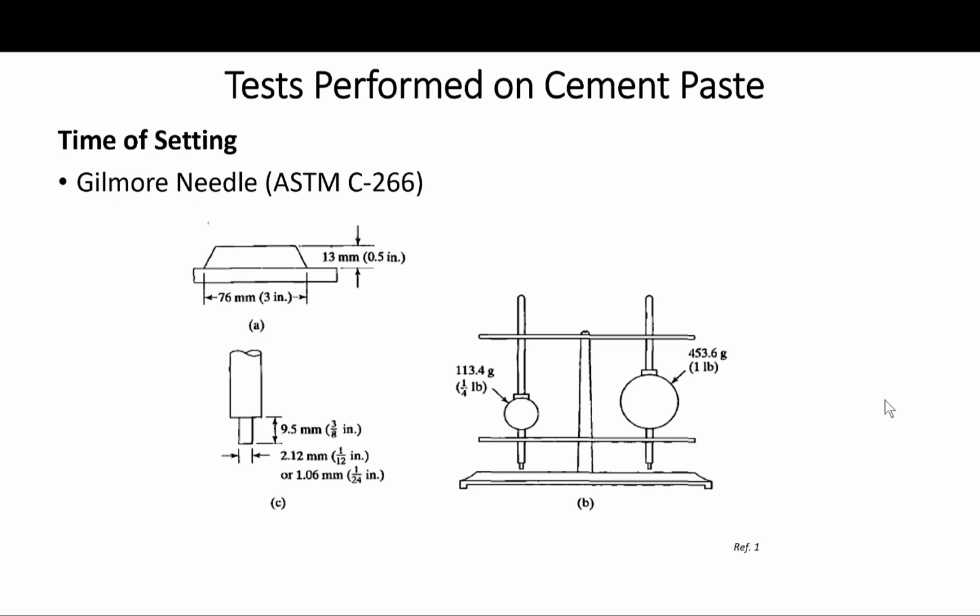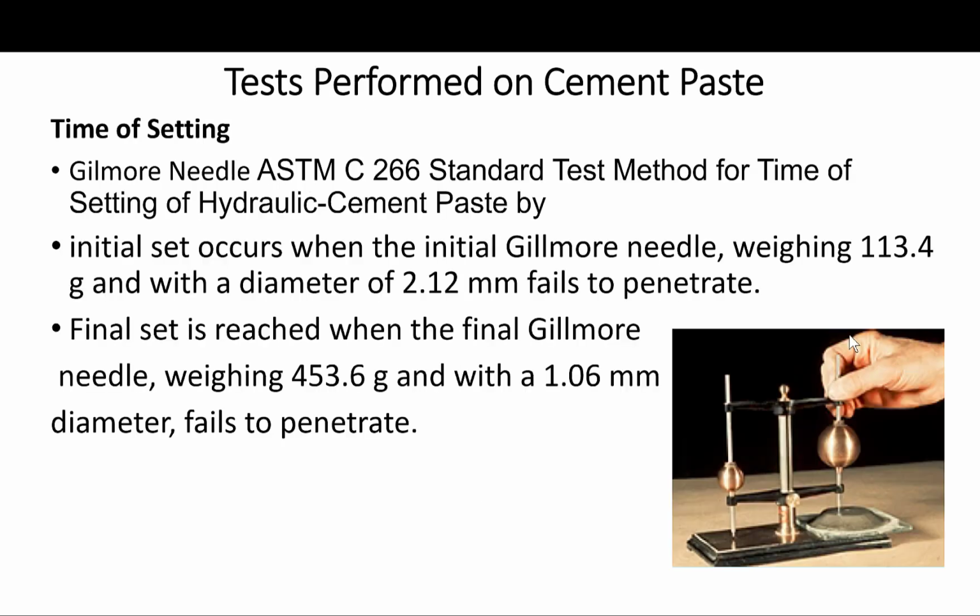This test is less commonly used than the Vicat test and gives different results. So you have to be careful what test is reported. The apparatus is shown here for the Gilmore needle. And here's a clearer photo of it.